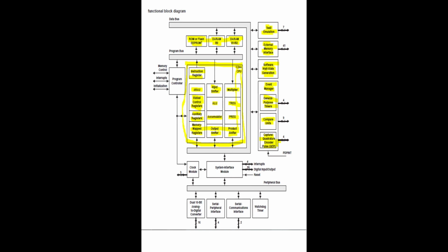So the current speed is given as multiple pulses. Speed is converted as pulse with the help of quadrature encoder pulse. That pulse will be given as an input for the DSP. So DSP is already having some set speed. That set speed will be compared with the given pulse from the quadrature encoder pulse circuit. Accordingly, the error speed will be generated. Accordingly, the speed of the motor will be controlled by generating the required PWM signal.